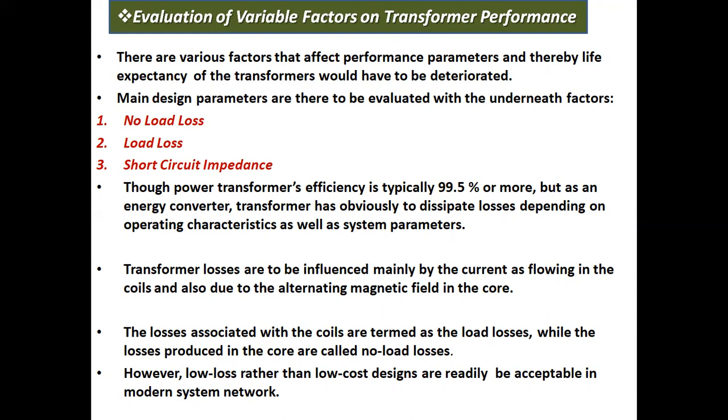Again, I repeat, the losses associated with the coils are termed load losses, while the losses produced in the core are called no load losses. However, low loss rather than low cost designs are readily acceptable in the modern system network.